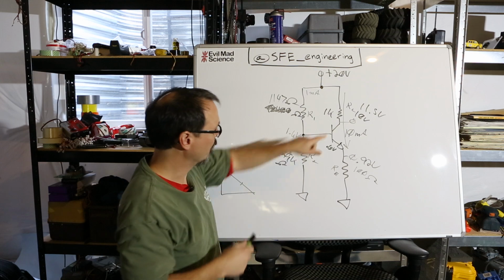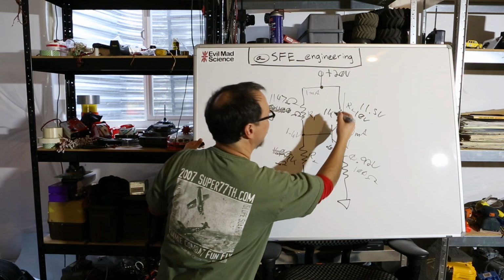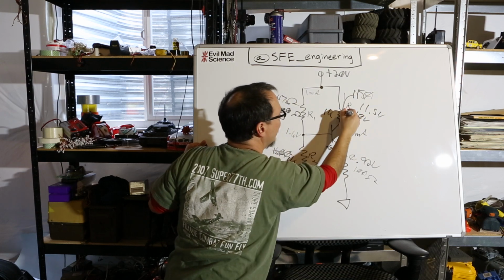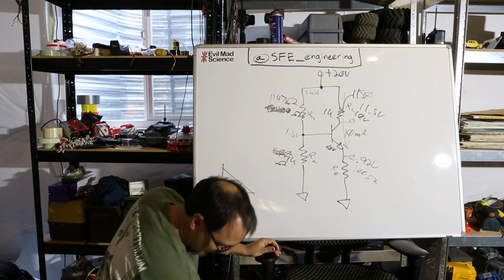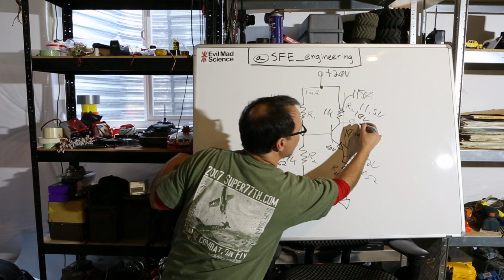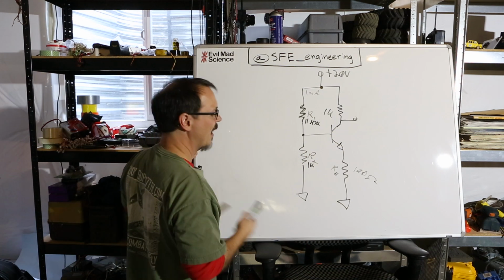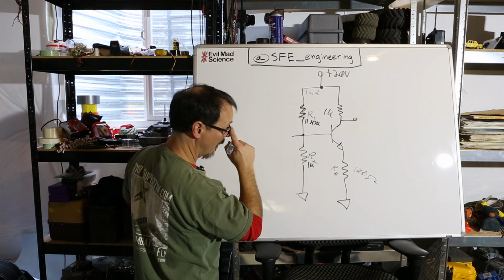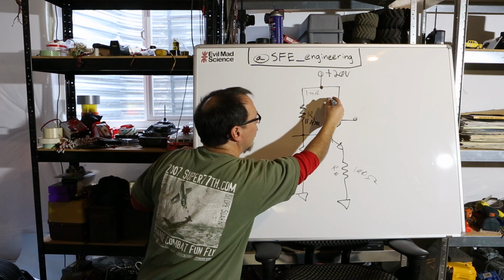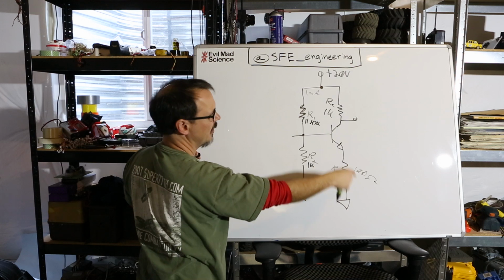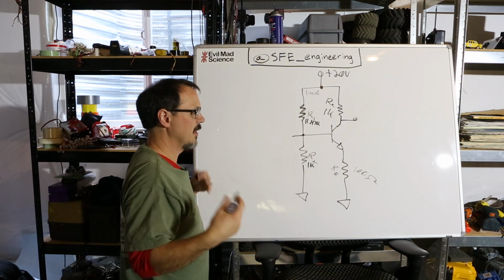So recalculating that value, 1150, I guess that makes sense, doesn't it? So 1150 became my new value for RC, and when I did that, I got my DC output down to 10.3 volts, okay? Now, as I've got this thing configured for gain, the input signal is going to be amplified by RC over RE. This is the gain. So this value over this value, 1K over 100 ohms, is a gain of 10.